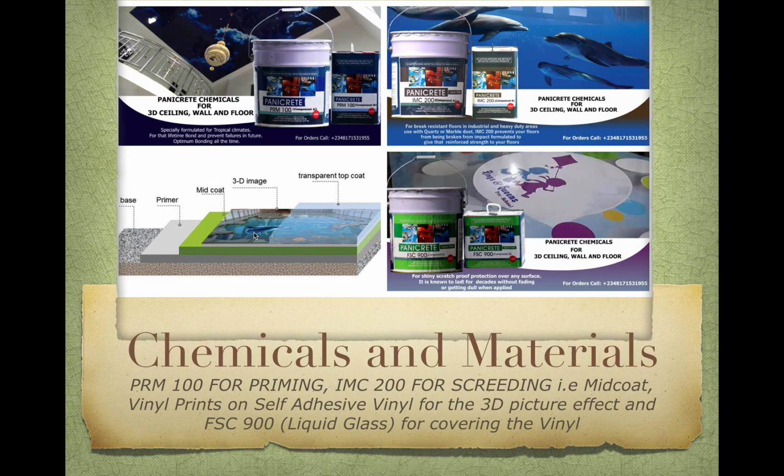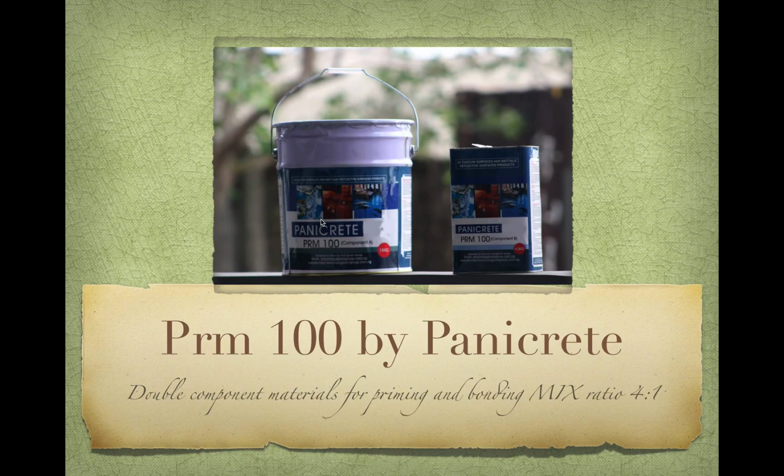They are all in liquid form. They are self-leveling materials. Once you apply them, they level on their own to give a flat surface, and they are used independently. You have an interval of a minimum of 12 hours before the next layer. For example, after you finish priming with the PRM100, you wait 12 hours, you do the mid coat with the IMC 200, you wait 12 hours, you install your 3D image. Then immediately after installing the 3D image, you install the transparent top coat. We'll talk about how to install them, how to mix them in the next lectures. But basically, these are the chemicals and materials that you will require in order to make your 3D floor.